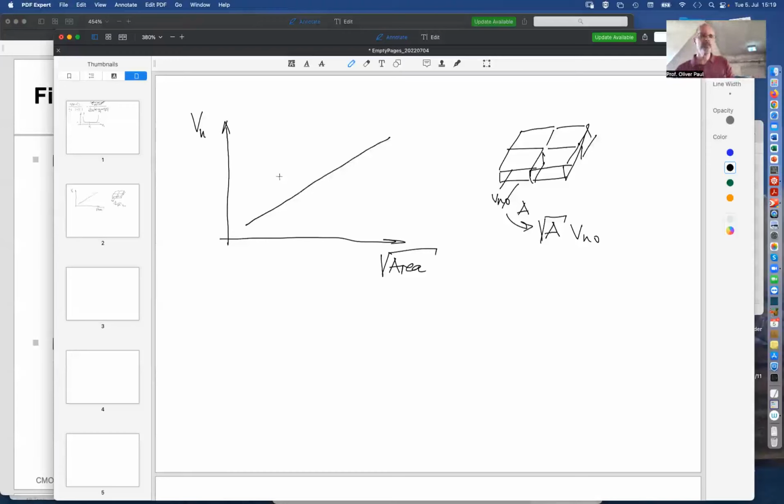So for one detector, you may have a curve like this. For another detector, you may have a curve like this. So this should go right through 0, 0. And then comes a guy and says, my detector has this noise, and I could also write here noise equivalent power. And then comes another guy and says, my sensor is better because it has lower noise equivalent power. But then the first guy says, yes, but your detector is larger. I can do almost as good as you with a smaller one.